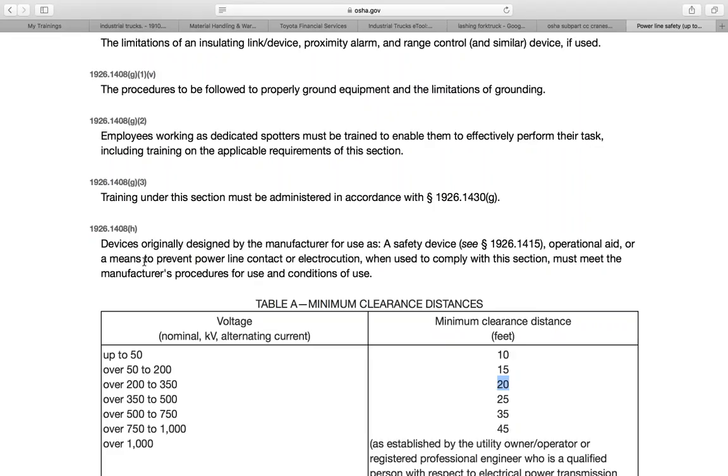And what's going to happen? That operator, the only time they're going to leave it is they're going to jump from the vehicle itself straight to the ground. They'll never make contact with the vehicle and the ground at the same time, and either they'll shuffle or they'll hop out of there. I've got that in a video. One of the videos that I'll send you tomorrow, or later on tonight, I'm going to send you some links on crane safety and rigging safety, and it's going to cover all this that we just covered.